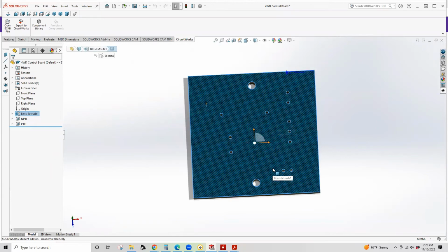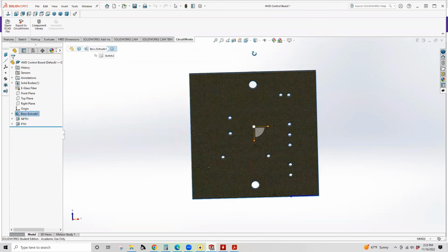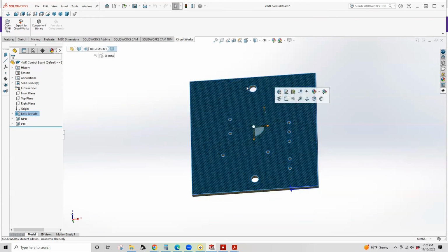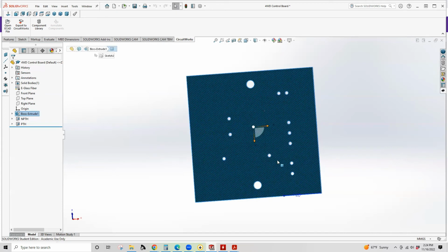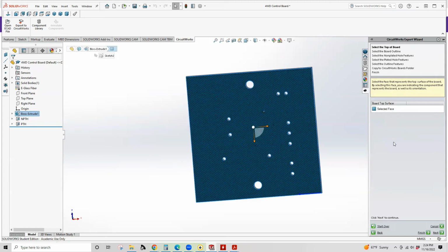Actually, this one, the way it's set up, is opposite to where this would be the top face. The way my board is soldered specifically, the resistor goes here at the bottom. The LED goes here, the motor power connector here, the power connector from the battery here, and the switch goes here. So this would be the top face.